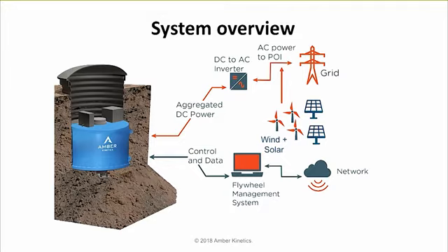It's basically an inverter. The motor wants an AC voltage waveform, and AC currents flow at the same frequency there. Frequency varies over the speed range for the flywheel. So if we have multiple flywheels, each one can have its own speed. They're normally very similar in speed, nearly identical, but they don't have to be identical at any moment.